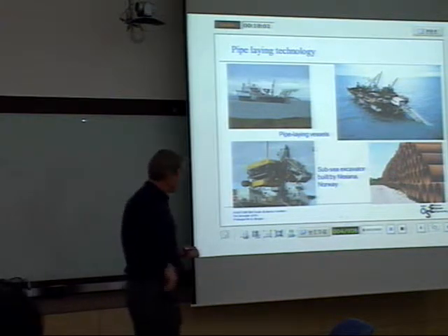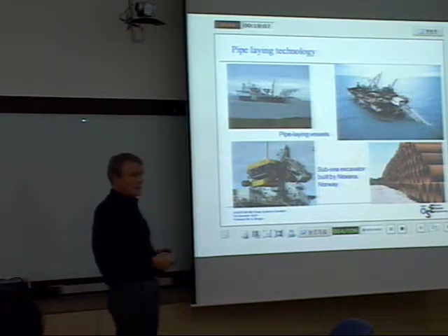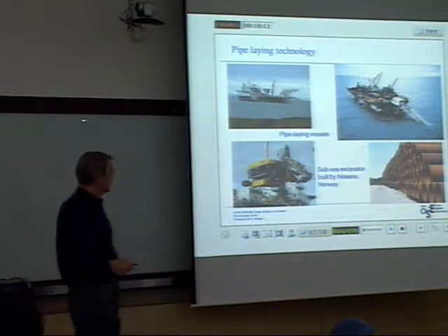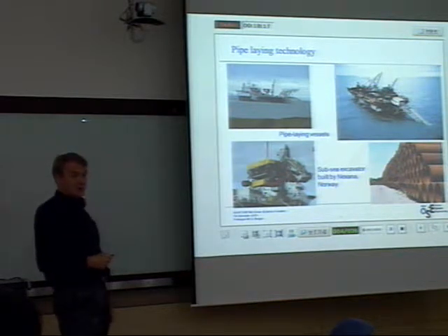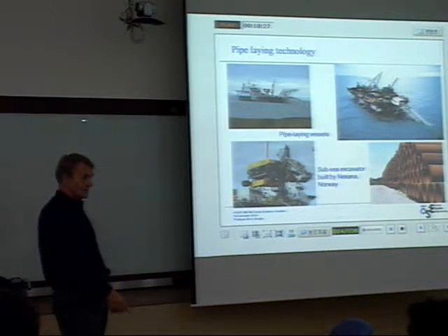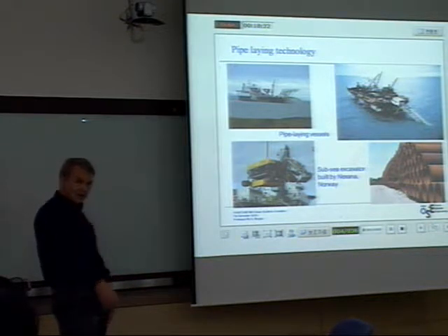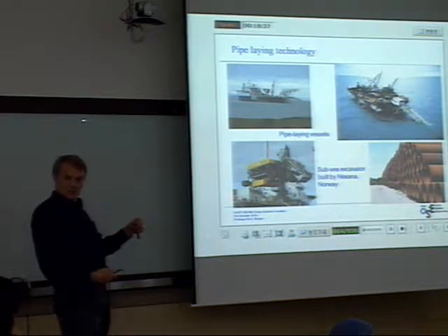So here you can see typically pipelines stored, and when you need 2,000 kilometers, how many pipes? This is interesting too. When you are closer to land, for instance in an area where there is fishing, you may have to dig and hide the pipeline in the soils on the seafloor. So you may have to excavate on the seafloor, and then you put the pipe in the trench.